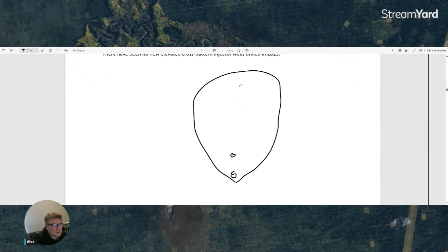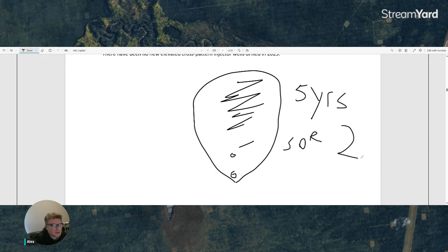We talked about IHS. So imagine this is one steam chamber. You inject steam over time, and let's say after 5 years, SOR is 2, and oil rate in this well is 500 barrels a day.